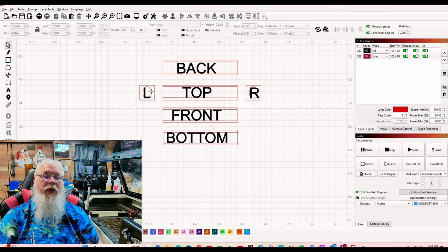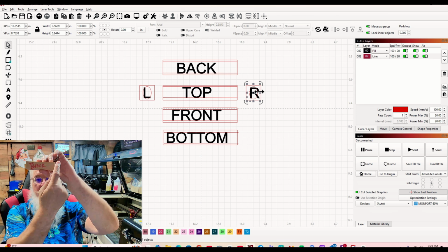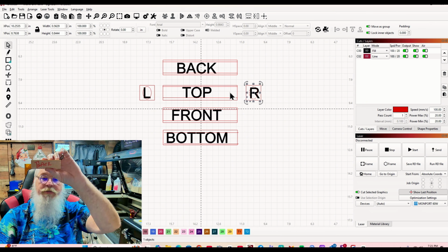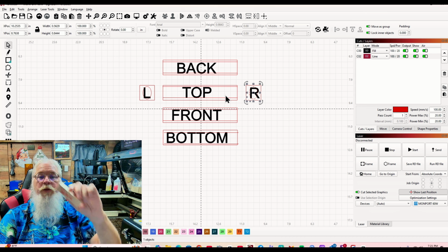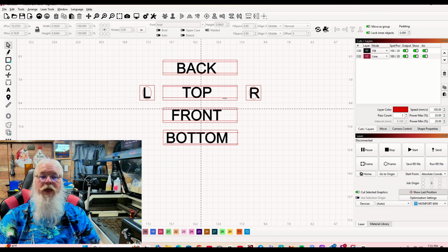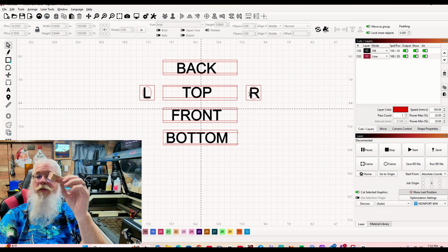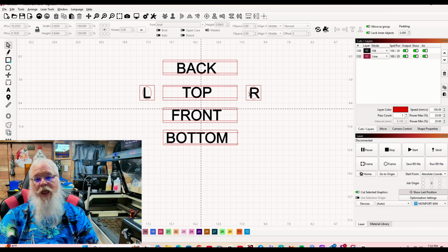And I have demonstrated that by doing this. These two circles represent a hole that has been drilled in one side, comes out the other. And these two lines that are here represent going through that piece. Now, normally, if it's embedded inside, these two lines here would be a dashed line saying that they're hidden within the wood, okay? So basically, every one of these lines inside here that you see in all four sections here would be hidden lines to represent that hole. Now, on the ends, they would be open because you could look at it directly and see that the hole was there. So that's kind of how you set this up.